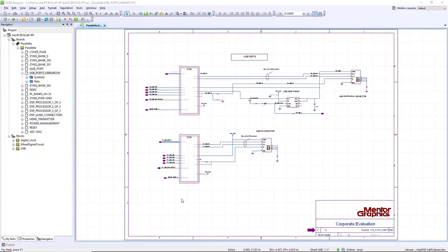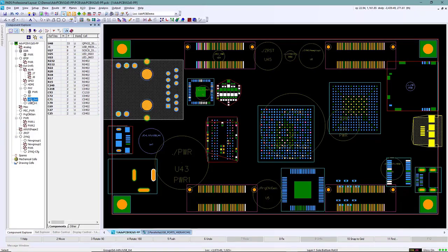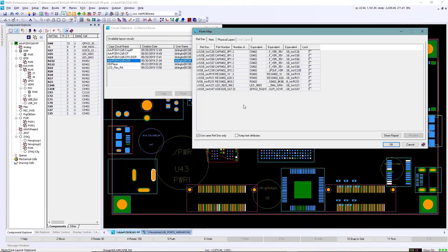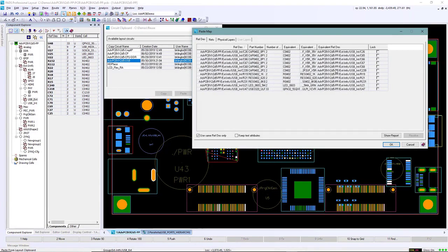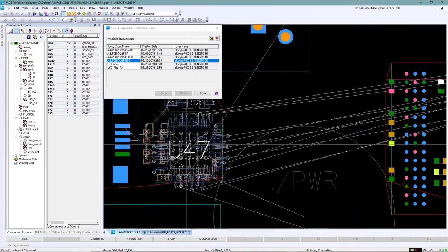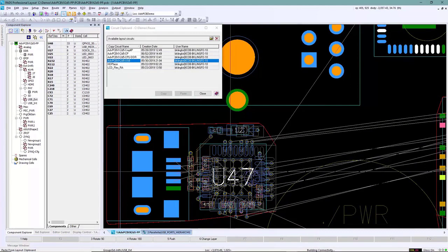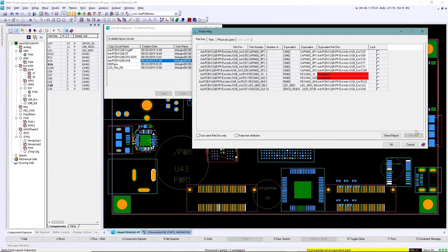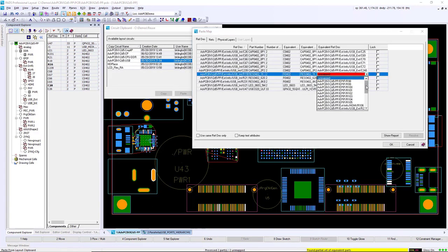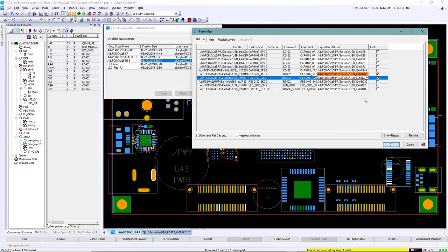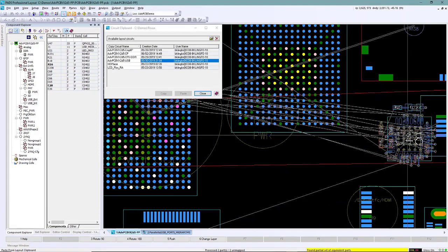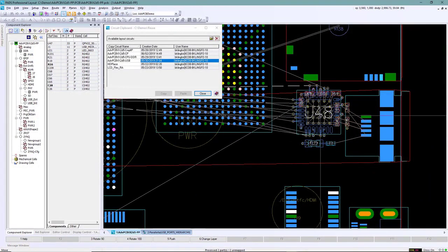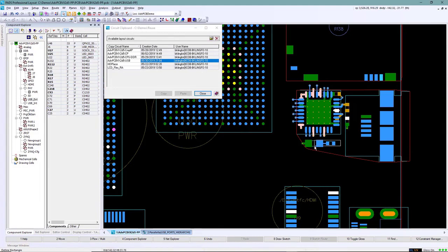If possible, we as designers should try to reuse circuits from one design to another. This is the ultimate in time-saving technique. Design reuse can be done from both schematic and PCB. For this design, we have two USB interfaces that use the same circuit. For layout reuse, all the items selected can be saved from a design which includes part placement, traces, planes, vias, drawings, keepouts, stack-up, manufacturing data, etc. If refdes values are the same, you have the option to automatically choose the correct parts. If there's no refdes match, you can try to auto-resolve the part selection.